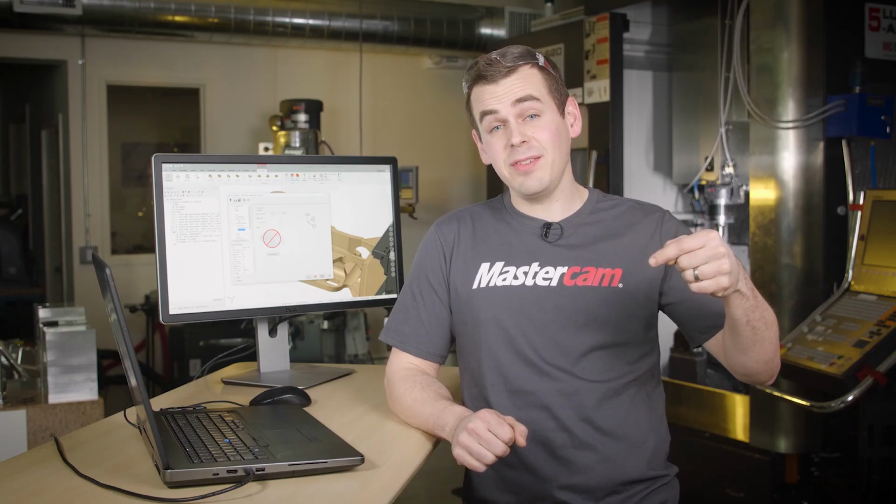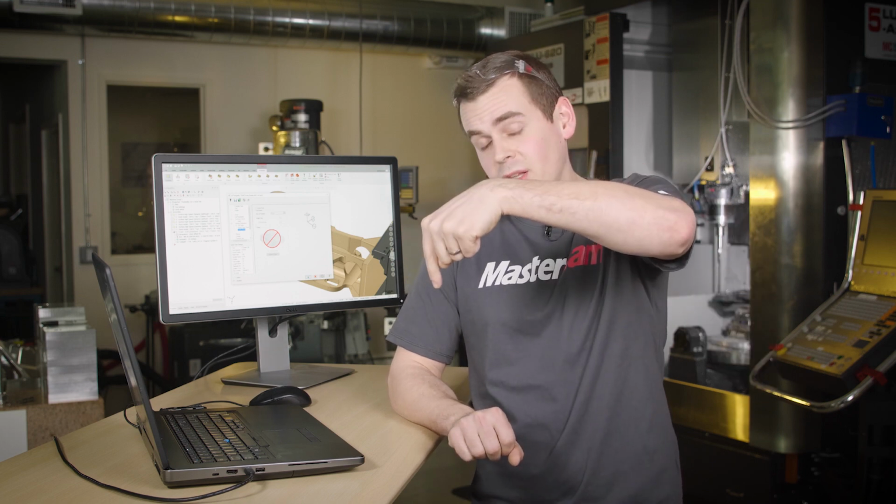If you're new to multi-axis programming, a safety zone is an area you can specify where Mastercam will not perform any linking moves. Instead, the tool will retract out past the edge of the safety zone, and only then will the linking move reposition the tool for the next cut.